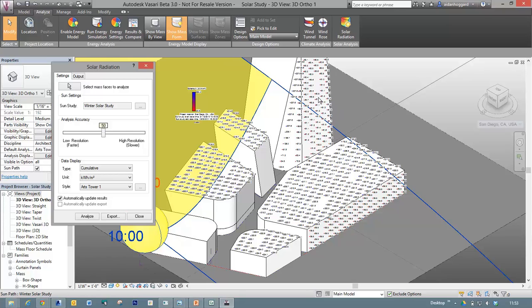And what you can do in a BIM environment, whether you're in Revit, or using something like Rhino, Grasshopper, you can create elements that will take their dimension from a parameter. So supposing you're designing a shading device on this facade, you could create that component and you could tell that component to take its depth from your figures that you're outputting here.